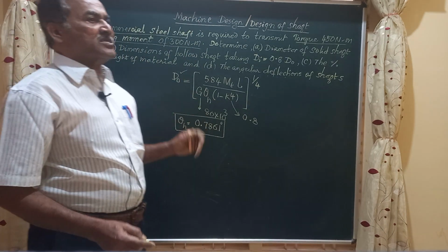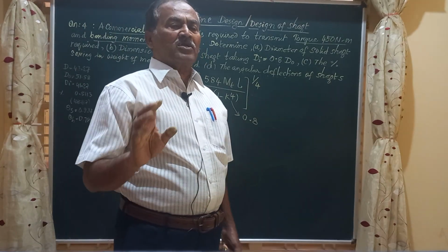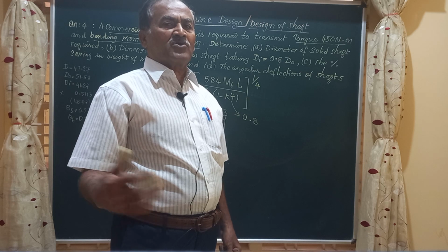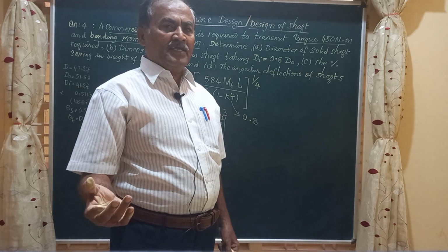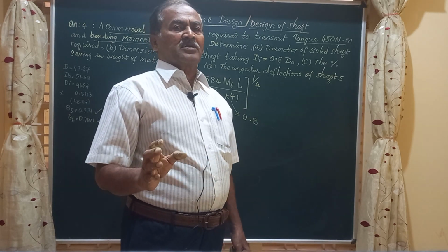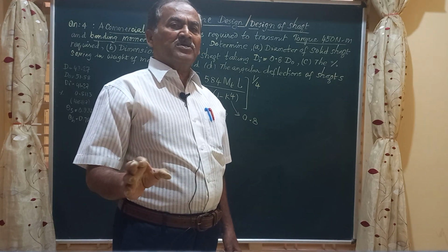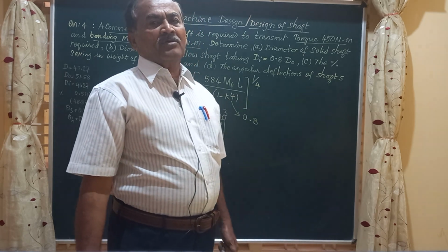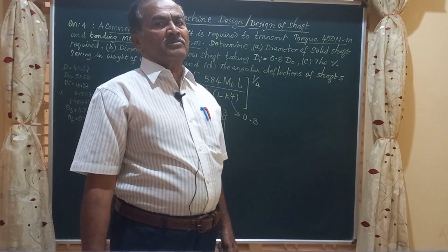That is, in all such cases, whenever a solid shaft and a hollow shaft transmit the same amount of torque, or just bending, or combined bending and torsion, it is proved that a hollow shaft is stronger and stiffer than a solid shaft. Thank you, friends.